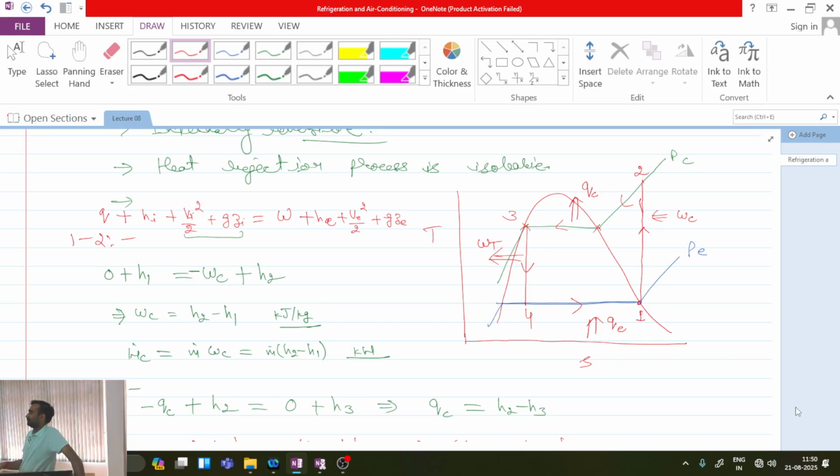Please tell me, what is the equipment or device used in place of turbine in AC? Expansion valve, generally we say. So in the older fridge or machines, a small capillary tube were used as expansion device. Nowadays we are having automatic expansion device, solenoid controlled expansion device, different type of expansion device. So first one question is answered that there will be some device which is called as expansion device.